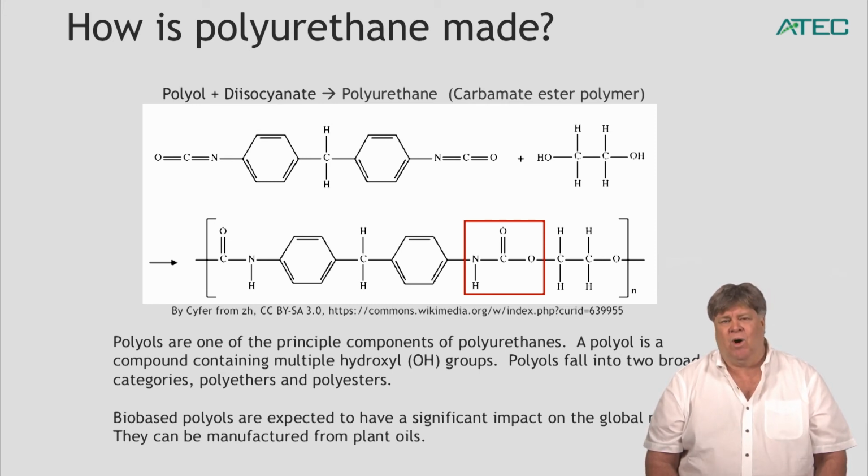And so this is done for petroleum, and so the broad classes of polyurethanes, in between the oxygens and the urethane bonds, we can modify the carbon functions in there, and they're usually either polyethers, which are carbons linked directly with oxygens, or they're polyesters, which are carbons linked with the ester group C double bond O bond O.